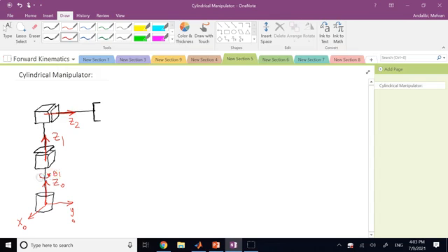And then you go to the next joint. Now for the next joint, as I said, the origin and the x-axis have to be determined by the DH convention. So if you look at Z0 and Z1, they are parallel. Therefore, the location of the origin for frame 1 can be anywhere along Z1. But the important thing is X1 has to be perpendicular to Z0 and intersecting it. And so I can select X1 to be either this one or this one, because both of them are going to intersect the extension of Z0, and both of them are going to be perpendicular to it. And as I said, to avoid twisting and to go with minimal parameters needed to represent the robot, I prefer to make X1 to be the same as X0 and Y1 to also be the same as Y naught. That makes life a lot easier for me, right? Because there is no rotation involved. Good. So this is my frame 1.